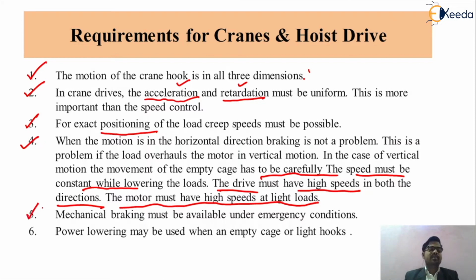The next requirement is that mechanical braking must be available under emergency conditions, because friends, as we have seen, such cranes and hoists are used for various applications, and in an industry there can be an emergency. So obviously, while we are designing such cranes and hoist applications, the drive must possess mechanical braking. This is a very important requirement while we are designing or selecting a crane and hoist drive.